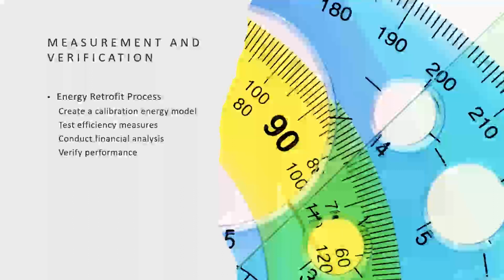Energy retrofit process. So this is where a building has been built. We build an energy model as it was designed, and then we build a separate energy model, the exact same one, and then we're going to try to calibrate that by feeding in real world utility data, occupancy schedules, and things like that to calibrate and see, okay, what happened? What went wrong, so to speak, or what change caused you to use significantly less energy or significantly more energy?